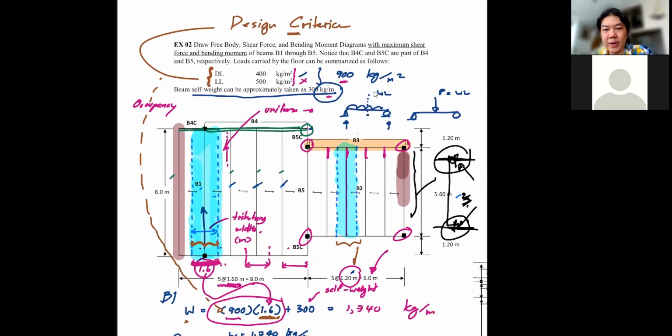generally, if it's a typical beam, except the cantilever beam, you should have 2 supports for each beam. You cannot have 1 support for a beam unless it is a fixed support. So you need to have at least 2 supports. In other words, it's your job to provide 2 supports for each beam.